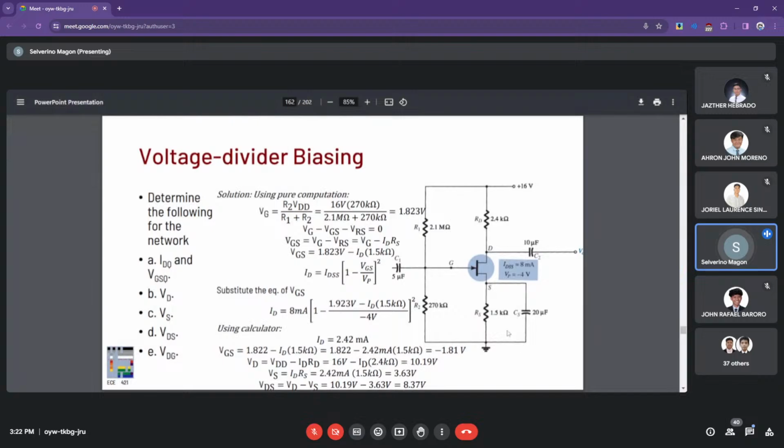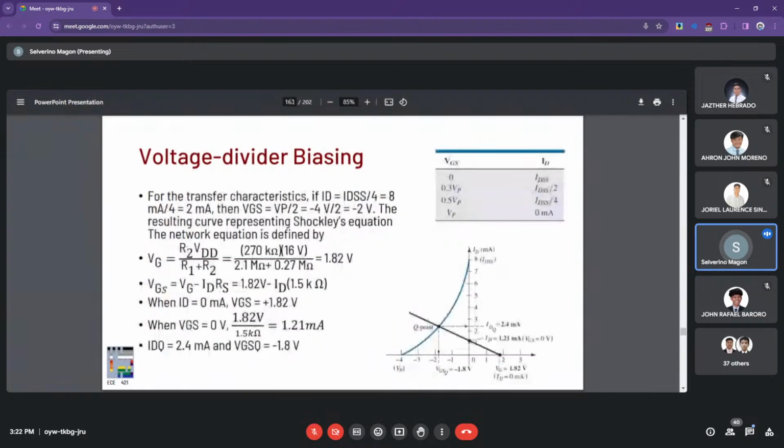You just see the capacitor right here as a bypass path, and so the voltage drop across RS is not being considered. Hopefully you're starting to build the idea now of how transistor action is being realized in the combination of the DC amplification and the AC later.